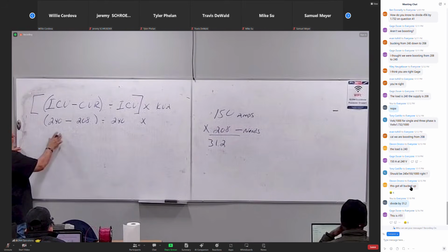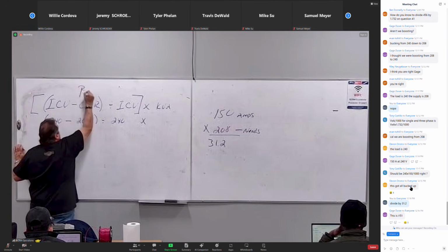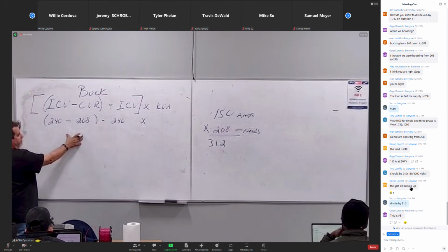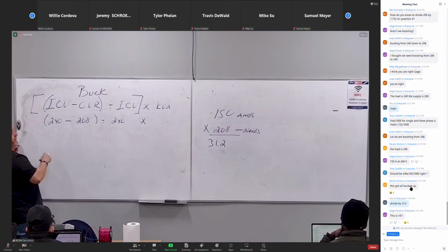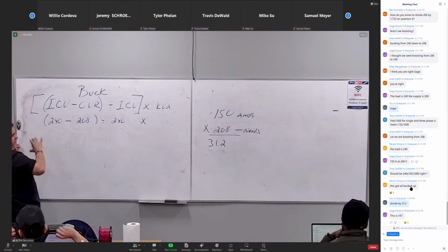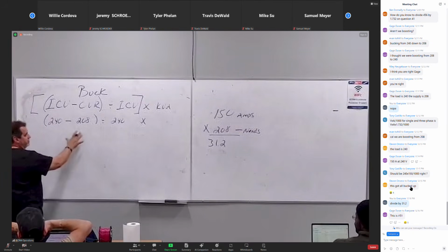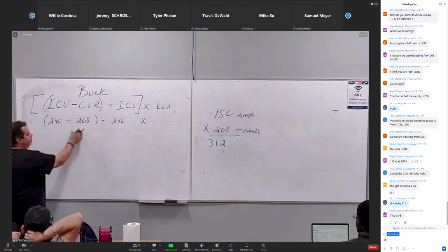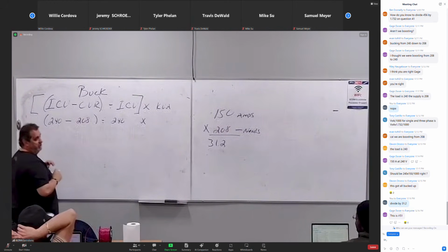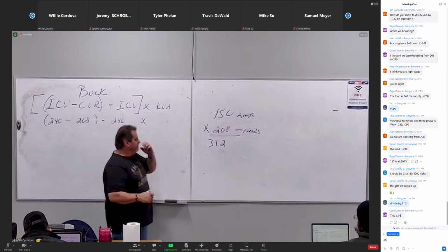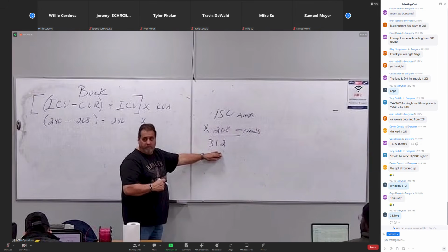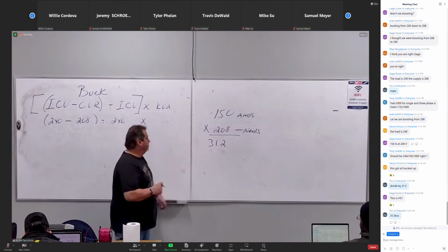We are bucking. Okay. When we buck, look, this is the formula we use. If we were given the information from the question, as far as amperage and certain voltages, this is what we're gonna go off of. Our load's 150 amps. It requires 208, we're supplying it with 240, so we're bucking. I have to calculate my KVA at what the load draws. The load is everything, not the transformer, the load. So we came up with 31.2.